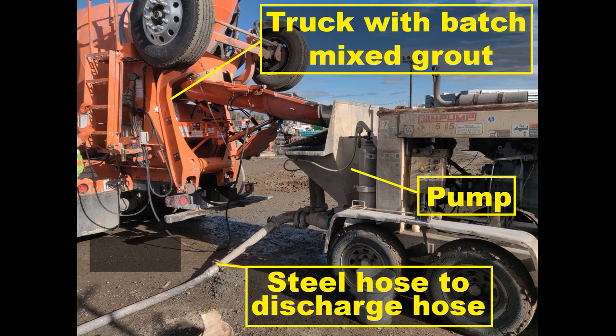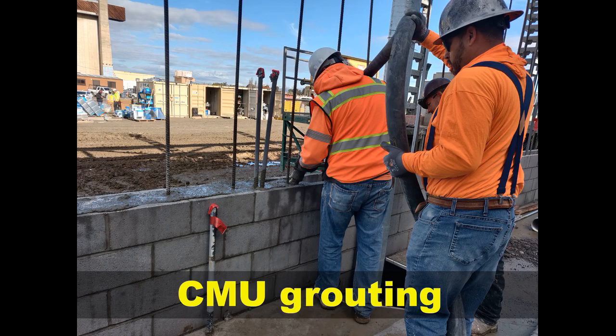Pumping grout through aluminum tubes is not permitted. Placing grout. Grout all walls solid full height or as shown on construction drawings. Discard site mixed grout that is not placed within 1.5 hours after water is first added to the batch or when the specified slump is not met without adding water after initial mixing.